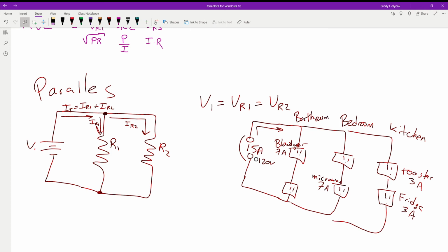Even with a 15 amp breaker, sometimes they don't blow when they should. They're old breakers, they stick, that kind of stuff. So they pull more and more current. Things start to get hot, and you're going to start to see your power drain a little bit. Your house usually has about 300 amp service. 200 to 300 amp service is a normal house or apartment. So you can pull a maximum of 300 amps through your entire house. So you always got to kind of be conscientious.